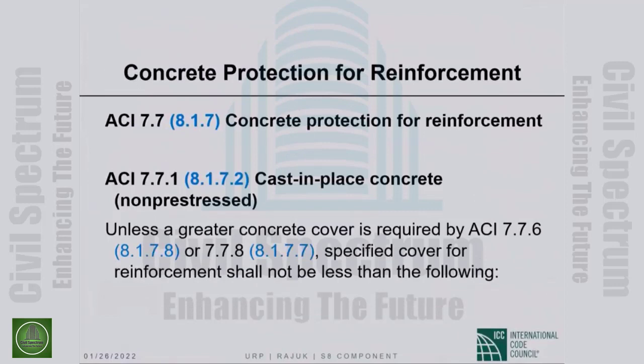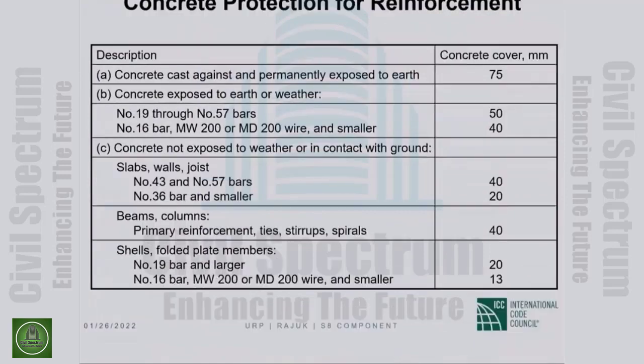Again, this is important. Unless a greater cover is required by special exposure conditions, if you are in a coastal area with a lot of salt in the air, that cover has to increase, and it may be that fire resistance requirements are such that the cover has to increase.